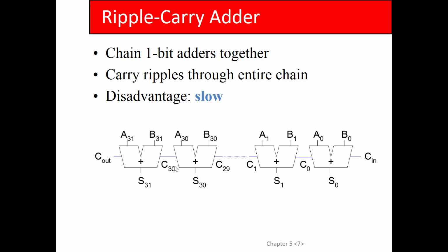And then I could do a little manipulation here. I can say, well, that's kind of long. What if I distribute propagate 2 out of there, and I can say propagate 2 and generate 1, or propagate 1, generate 0, or propagate 0, carry in 0.